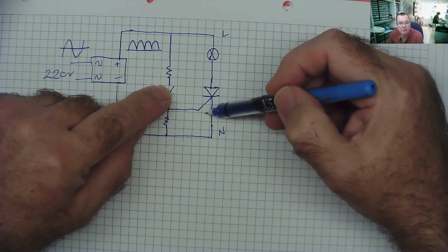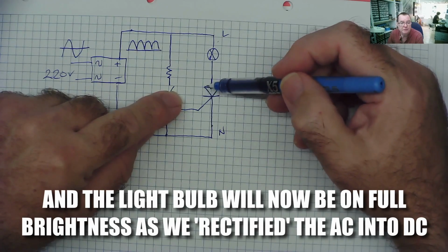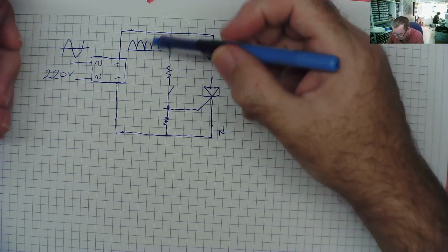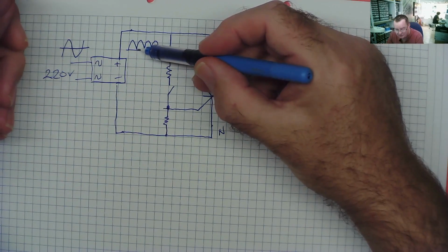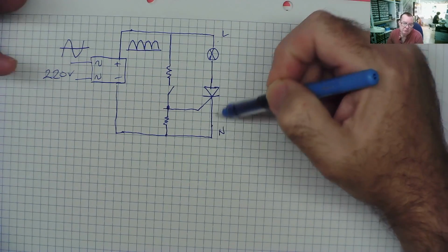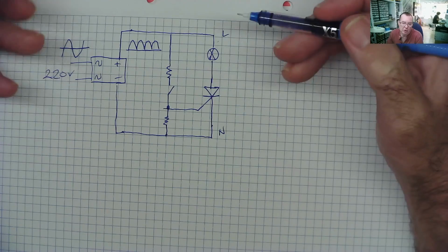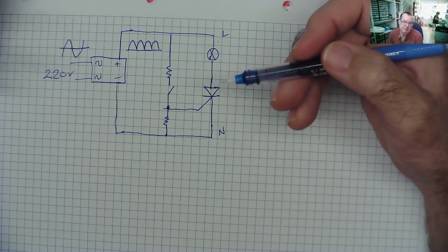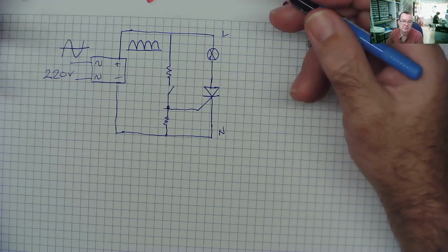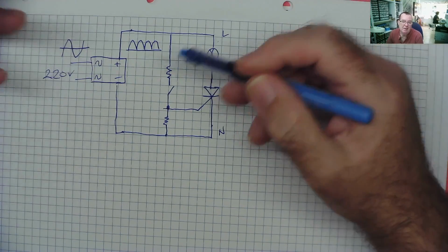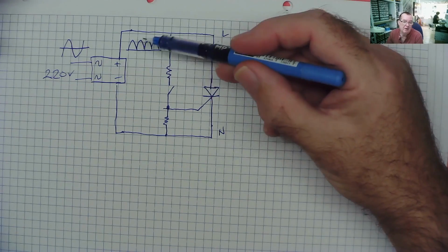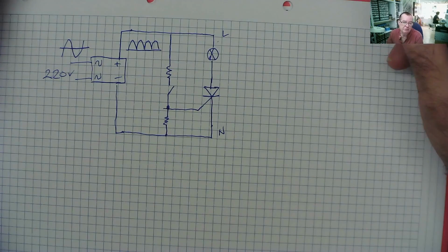this will turn on. When we open the switch, it will stay turned on as I just described, but only until the input voltage comes to 0, or more technically speaking, the threshold current is not reached. The current flowing drops below the threshold. It will then switch off, and it'll stay switched off until we close the switch again. It'll switch on again. So this is now acting like the enable signal, and it's doing so because we have a pulsed DC voltage coming in.